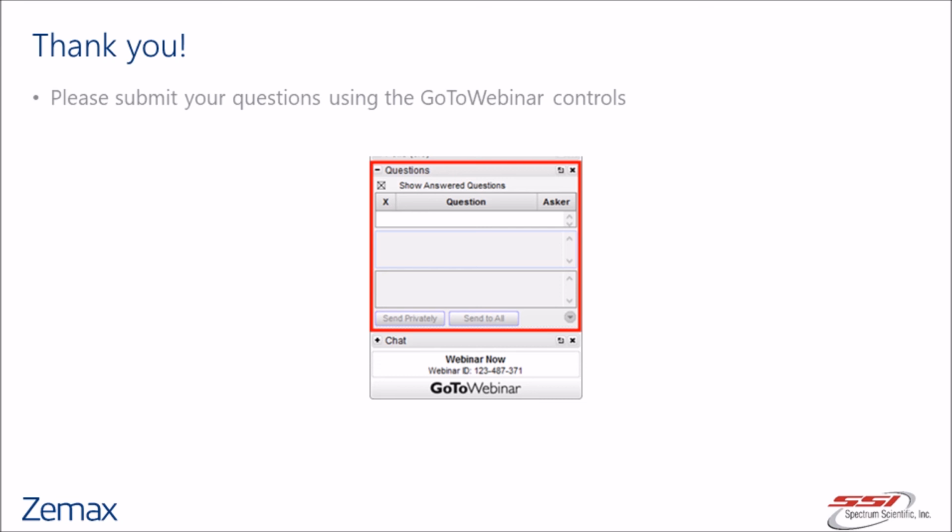So you might need to go back and calculate the RMS irregularity that you introduced during that tolerancing. You can also use scripted tolerancing to control how the coefficients are added to the part. That's a little trickier, but then you can control the RMS that you're introducing during the tolerancing.